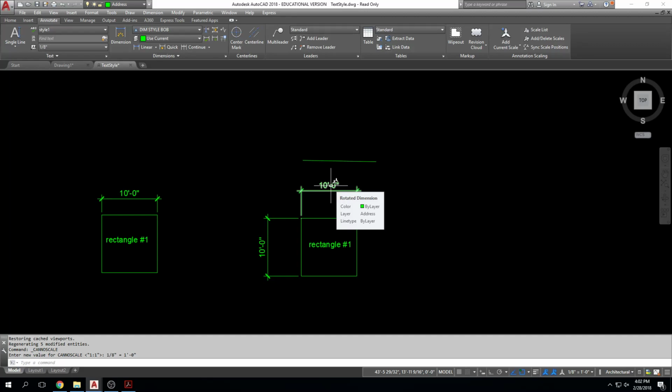1:1 has a 1 scale factor. So the 1 scale factor, it's not even zooming. It's just like viewing it at a 1:1 scale. So the text can be really small. It's going to be 1/8 of an inch because it doesn't have to zoom in and out. But the 1/8 inch scale has to zoom in or out 96 times to get it to the right scale. So this can be viewed at that tiny scale and look right. And this one has to be really big so that when you zoom in that far, it looks tiny.